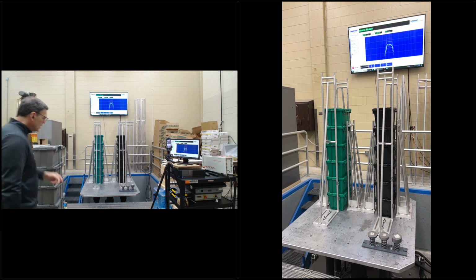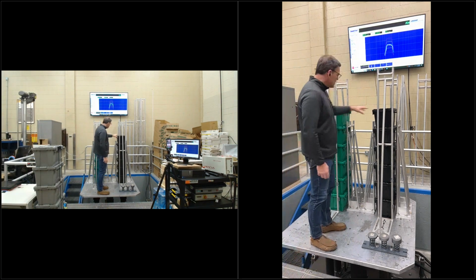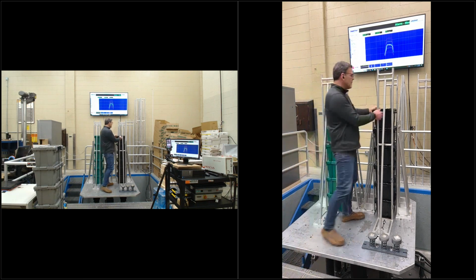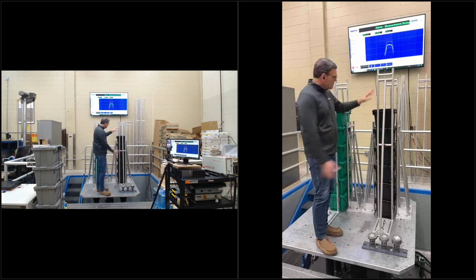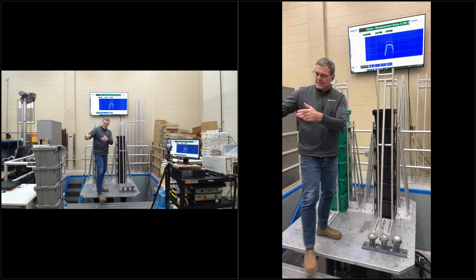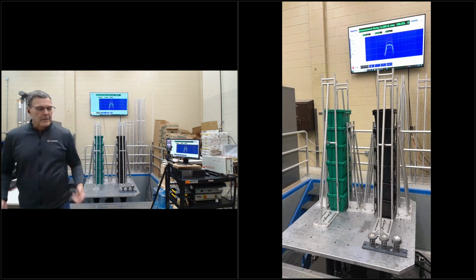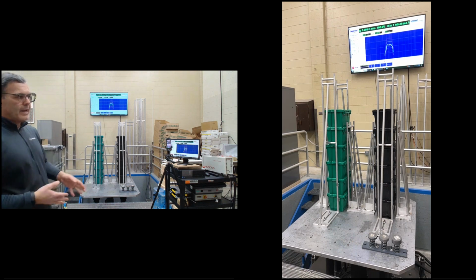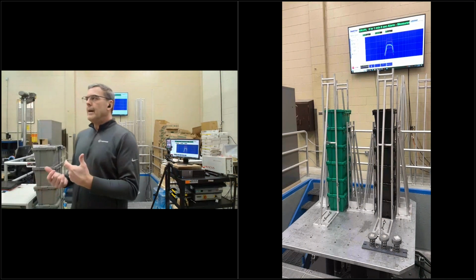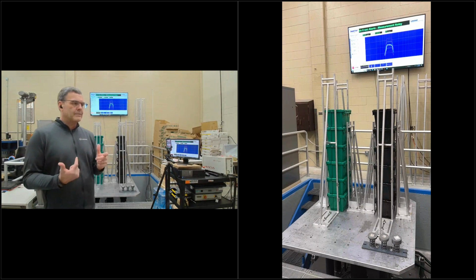These are heavier than these guys, so the natural frequency of this is still lower than this, but higher than that. When you talk about the natural frequency of a spring-mass system, you can think of it as bigger, heavier items having lower natural frequency, and lighter things having higher natural frequencies. So if you're talking about testing individual layers or individual packages, some of the trade-offs.